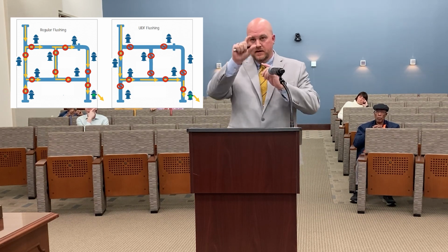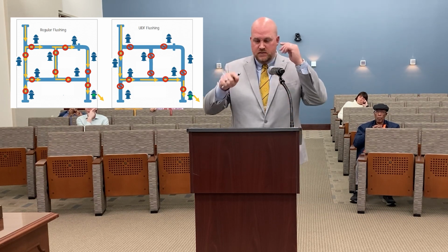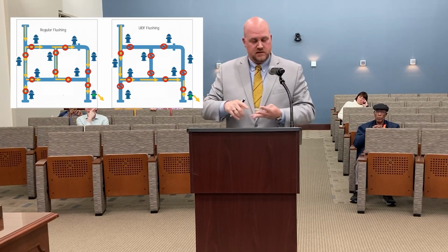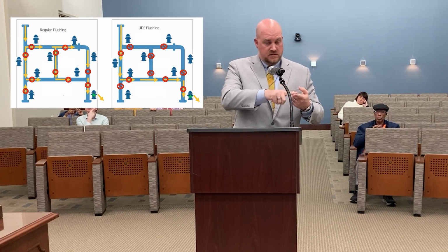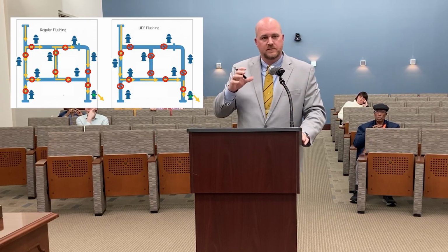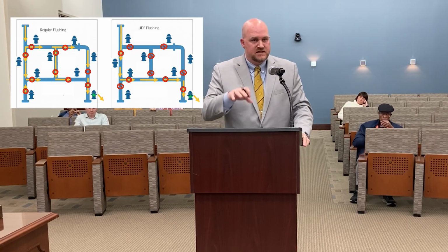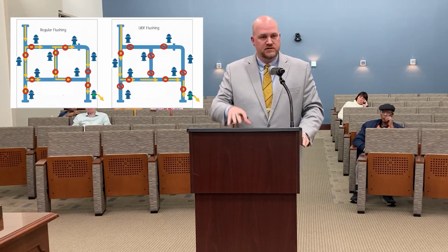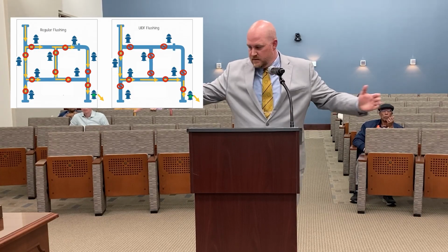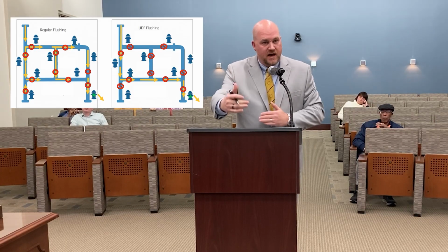So you'd say, to clean Davis Street, you need to close valves 1, 2, and 3. To close C Street, you need to go on and so forth. So it develops a specific, dedicated task, a dedicated standard operating procedure for each road, each section of pipe, each hydrant.